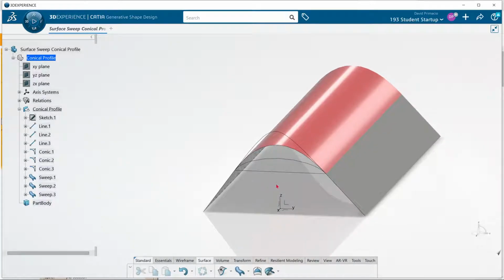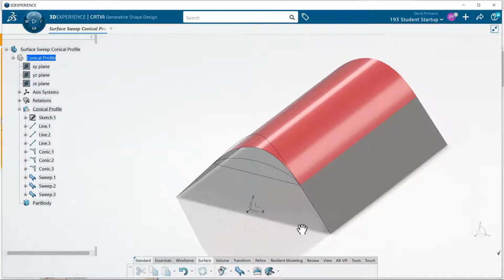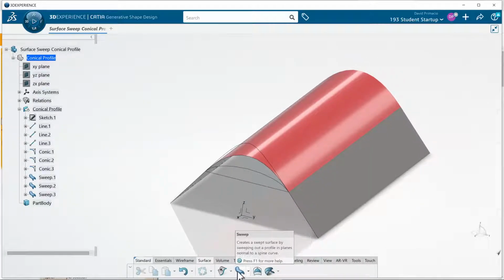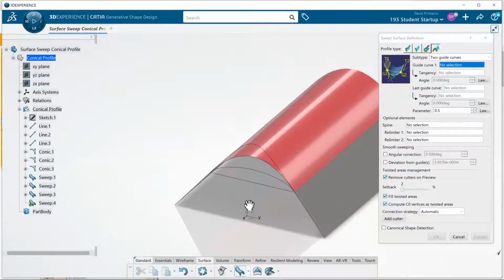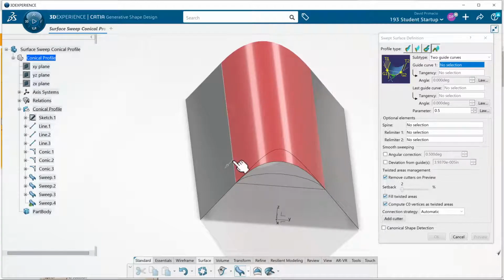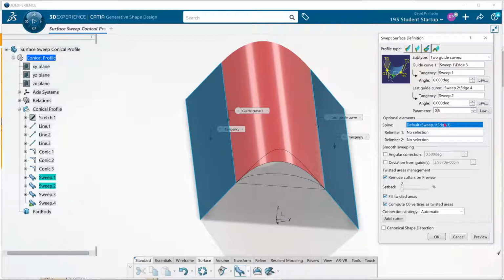Let's say you had something underneath this and this was hitting it, so you actually need to create something further up. That's when you just simply create a different parameter value. I'll do this 2 more times. So in this case here, it was this guide curve, this surface, this guide curve and this surface, and then we will do a parameter of 75.